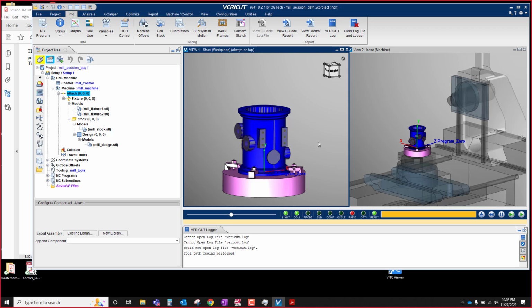So you run your standard program, it runs optimization in the background, and it builds an optimization file. Let's say you've got this cut going through the material, and there's one area where it spikes the load or something like that. It'll actually break. So let's say you've got one line of G-code that goes from X1 to X10, right? And there's a section in there where it encounters a taller wall, and that taller wall is causing a spike in load on the cutter. It'll actually break that single line of G-code into multiple lines of G-code, each with its own feed rate.